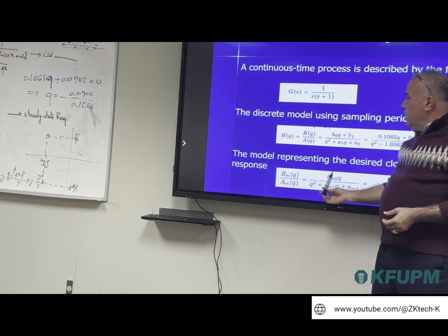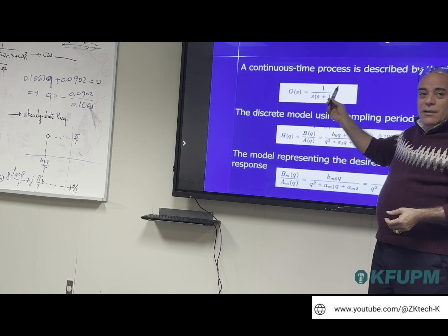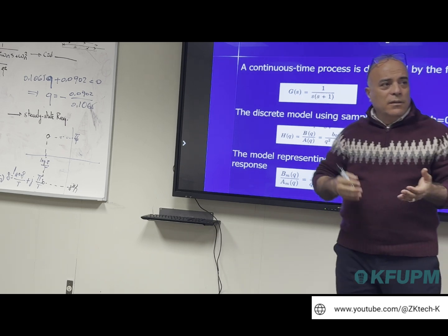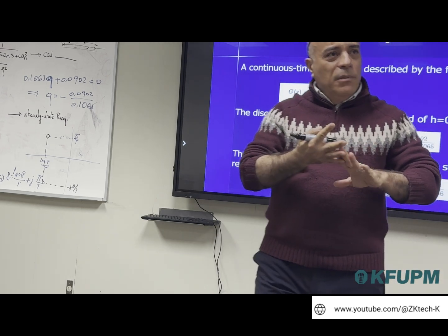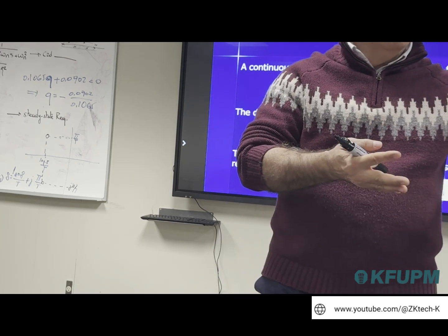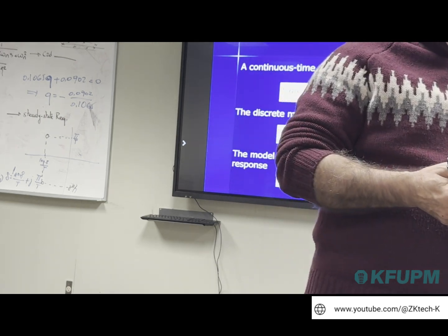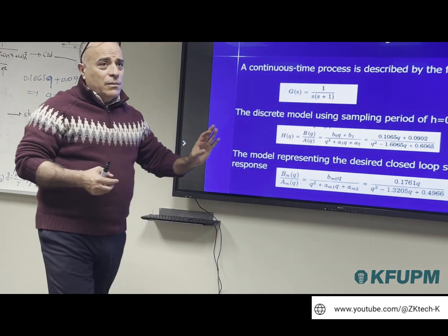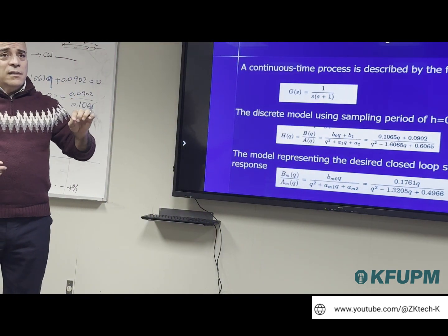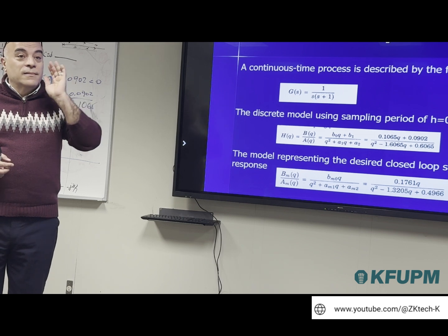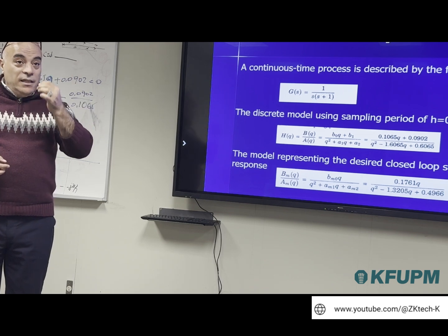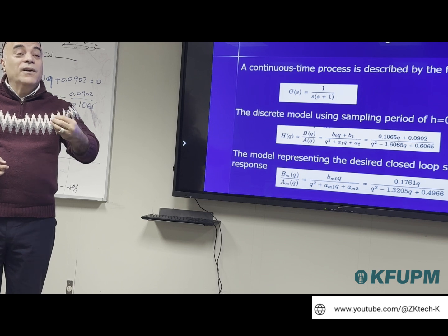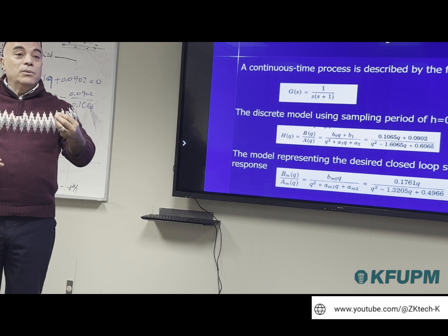Another thing, like what we did here, we add the q minus 1. There are many techniques, and you have seen this maybe in your bachelor degree. There are 3 ways to do this. Either you keep it as a constant, or you add q, or you add q minus 1, and all of them are valid. The way we use discretization in MATLAB gave us the zero. So in the discrete, this zero is a valid dynamic due to the discretization.